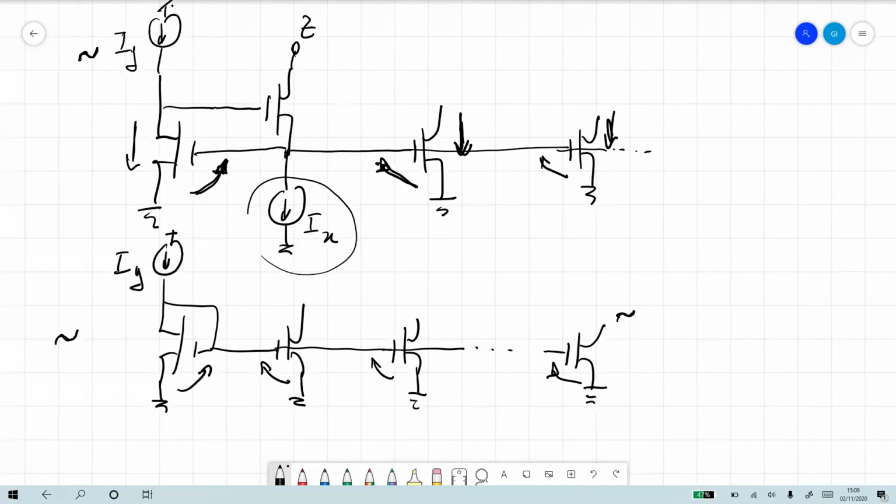And so if you think of it, when you implement this in silicon, all of these gates and all of these wires going across will actually add a lot of capacitance. It's called parasitic capacitance. It's not explicitly drawn there, but you actually have it because you have lots of gate to source voltages. And so now, because your signal is the current, whenever you try to change your signal because your input is changing over time, you have to charge and discharge the capacitor.